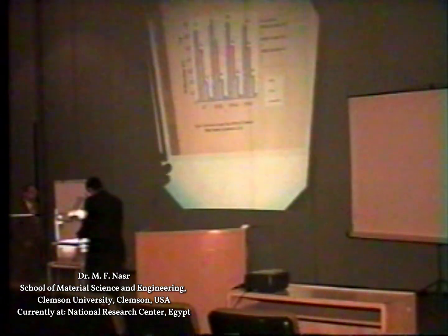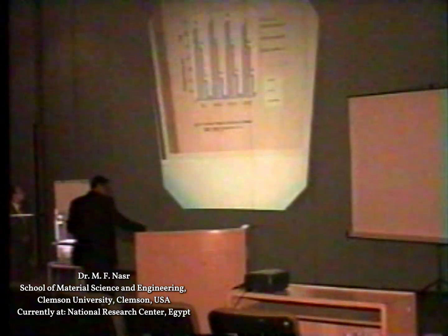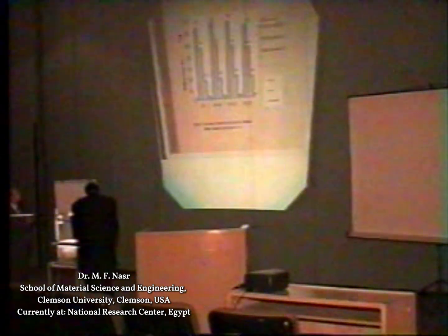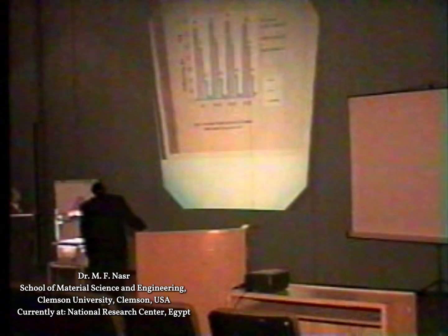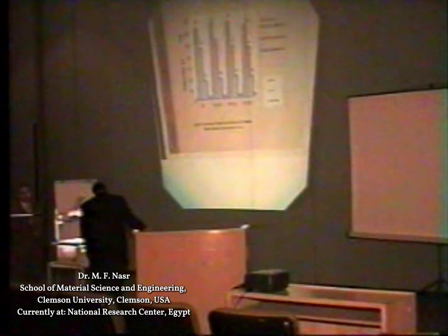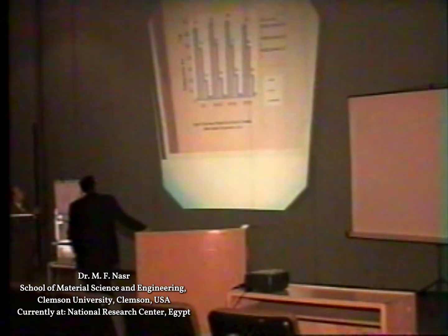By looking at the surface area, and like I said, this is the most important criterion and we need to keep it. So we have to study the surface area of ACF with the heat treatment. And here we can see the ACF without treatment, or as received. We started with 1216, and at heat treatment at 300 and 600 it increased, which is kind of expected,